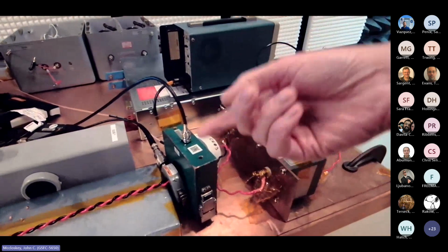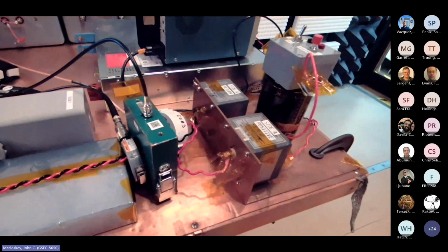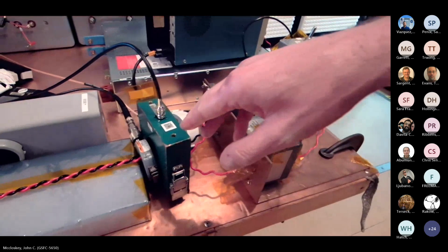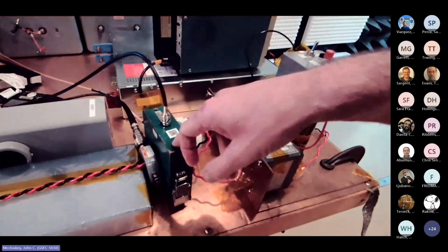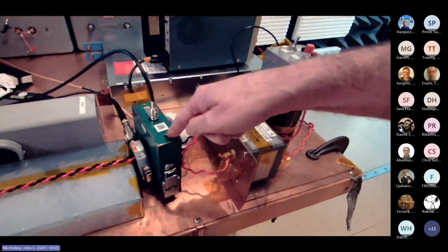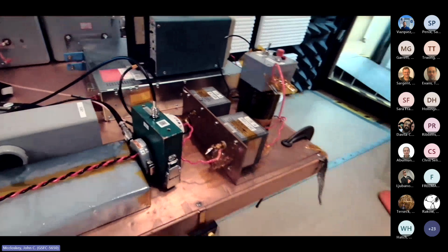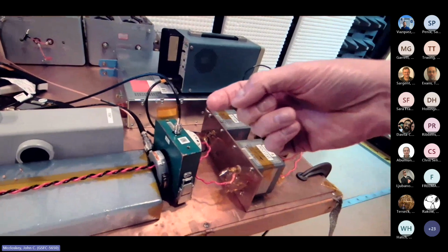So you hook this thing up to a scope and measure what kind of current you're picking up from a lightning strike, or events like that. And so if you're using a current probe like this in the time domain, you want to make sure it's got a flat frequency response over the frequency range of interest. This probe has a specified transfer impedance of 100 milliohms into a 1 megohm load.